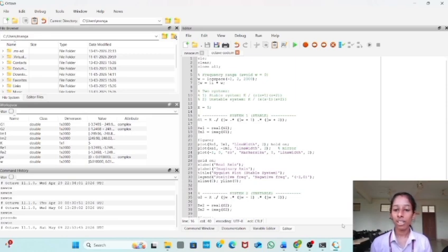One such powerful technique is the Nyquist stability criterion, a graphical frequency domain method used in control systems to determine whether a system is stable or unstable. It works by analyzing the Nyquist plot, which is obtained from the frequency response of the open loop transfer function. The stability of the system is determined by observing the encirclement of the critical point in the complex plane. If the plot does not encircle the critical point, the system is stable. If it encircles the point, then the system becomes unstable.